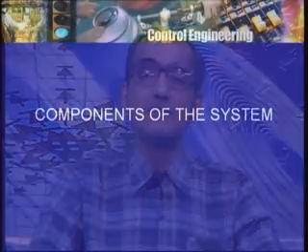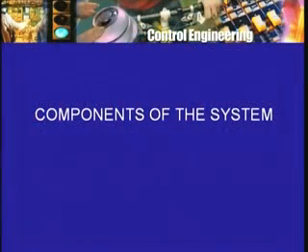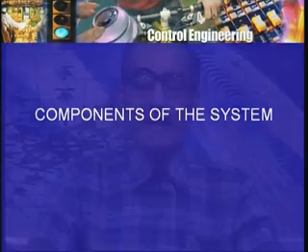Now in order to do this, of course, what one does is, first one looks at the components of the two systems. In the electrical circuit case, the components are simply the resistor, the inductor, the capacitor, and the voltage source. For the mechanical system, the components are the mass, spring, dashpot, the support to which the mass and the dashpot are fixed, and the driving force or the displacement source, as sometimes it may be thought of. That is, rather than force, you produce a motion of the mass and then see what happens.